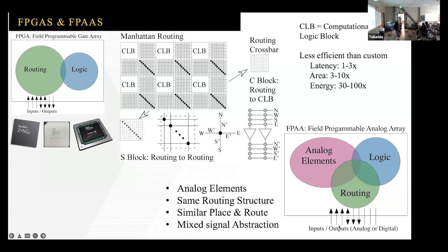Picking up in a similar direction to what Andreas was saying: when I was at Furber's lab, we were building a chip, or starting to build a chip, that stretched up networks of spiking neurons. And the big discussion we always had is exactly the question of fan-in and fan-out, because the number of wires explodes, right? And like the n squared number, I'm not sure exactly where this comes from, but as you scale it up, you have longer distances and more neurons that you want to connect, right? For us, I think we ended up with like 1,000 neurons, 25 in-degree. And I'm wondering, is there a way to go to bigger networks?